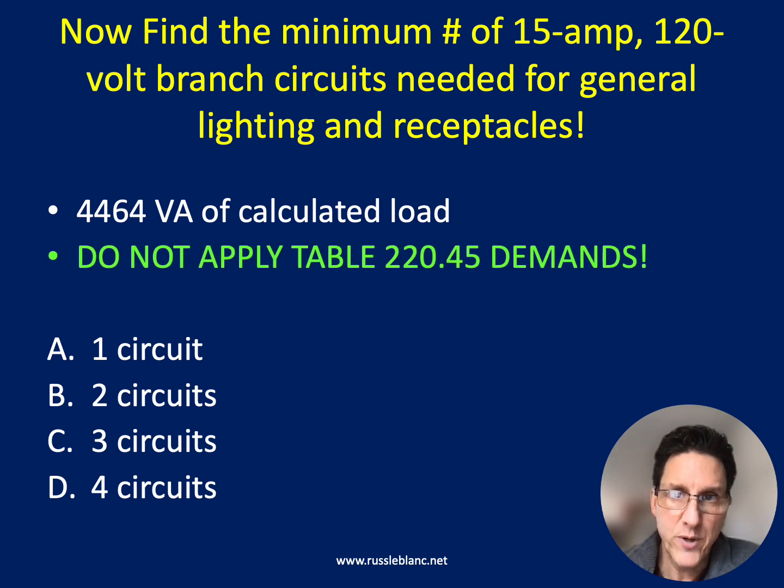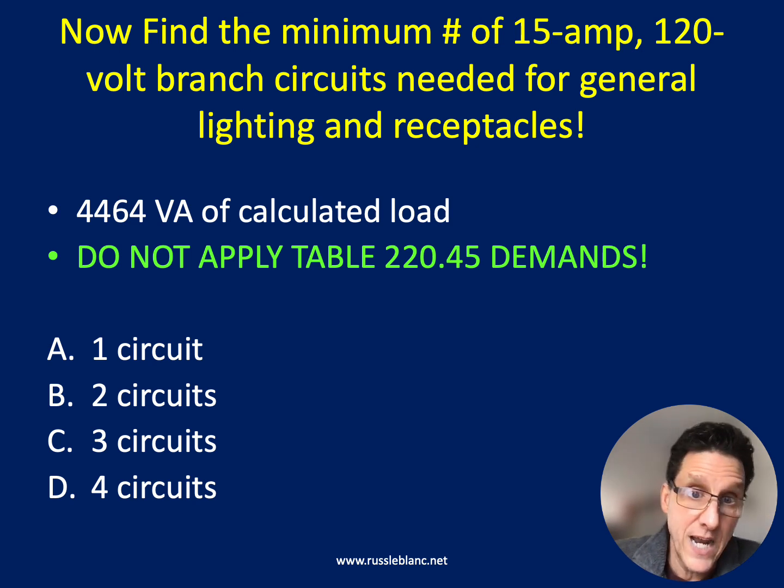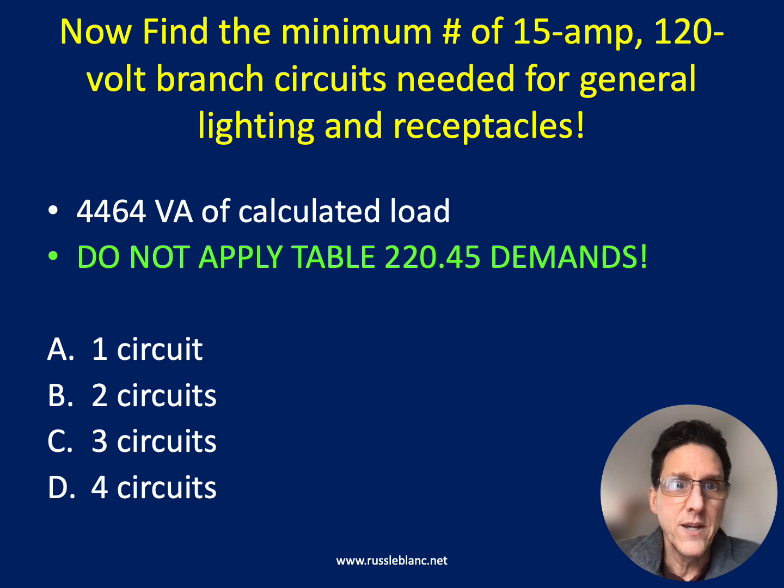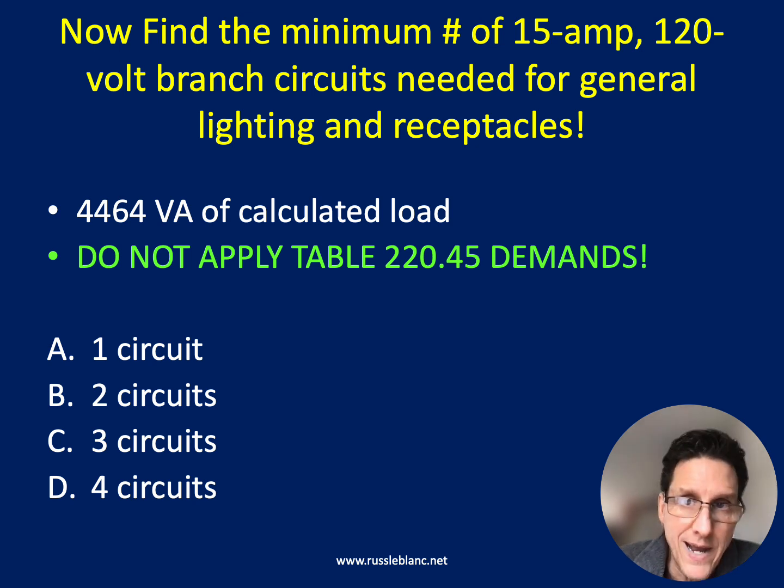Now, I want to point out, do not use the demands in table 220.45. You can do that if you're sizing a feeder or a service. We're not doing that, right? We're only calculating the number of branch circuits, so you don't get to apply the demands from 220.45. And that section even says that: this table shall not be applied in determining the number of branch circuits for general illumination.